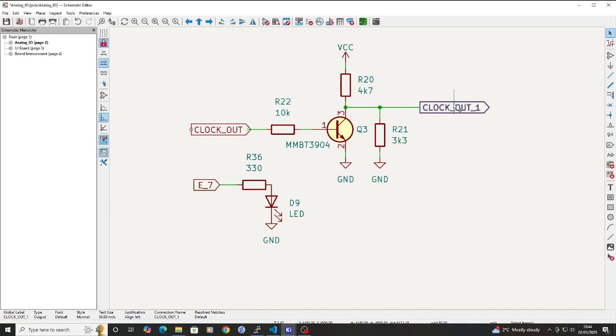So the ultimate clock output is phase inverted compared to the pin from the Pico. And separately, I was using another pin to drive the LED, and when this pin goes high, the LED comes on. So in order for the LED to come on when the clock output goes high, I needed to invert the phase between these 2 pins, which I was doing in software.